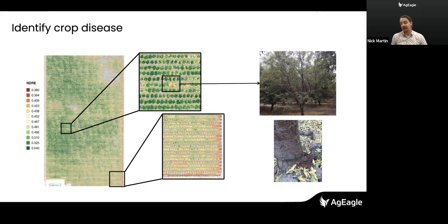Professional cameras like MicaSense cameras allow you to capture extremely high quality, high resolution images with a ground sampling distance typically of about 8 to 10 centimeters per wavelength, per band, when flying from 400 feet AGL. So you're able to differentiate between plant canopy, the shadow of the plant, and the soil as well, as opposed to just combining all of these elements into a single pixel and providing an average, which is something we don't do.